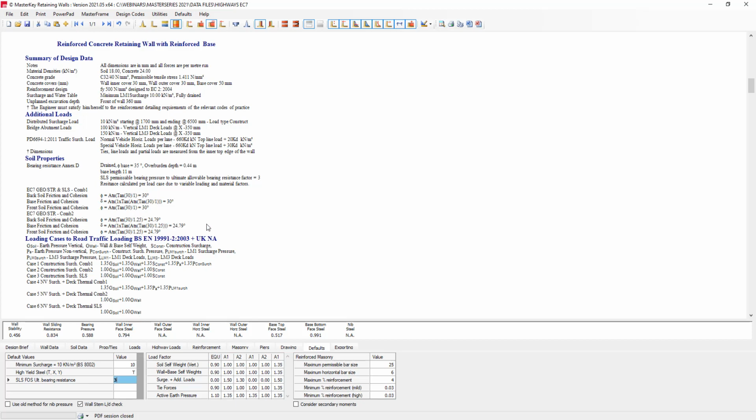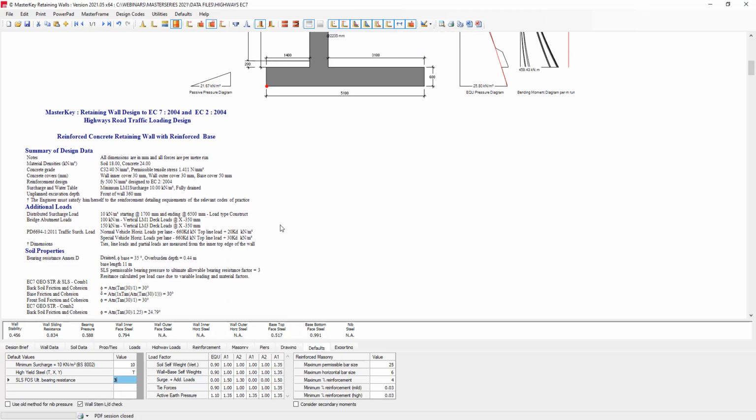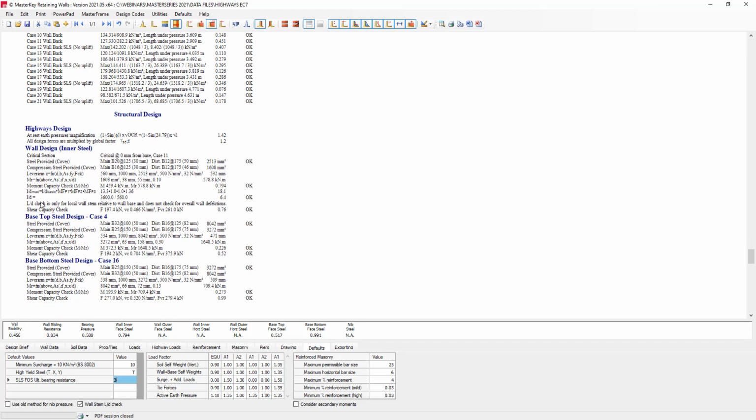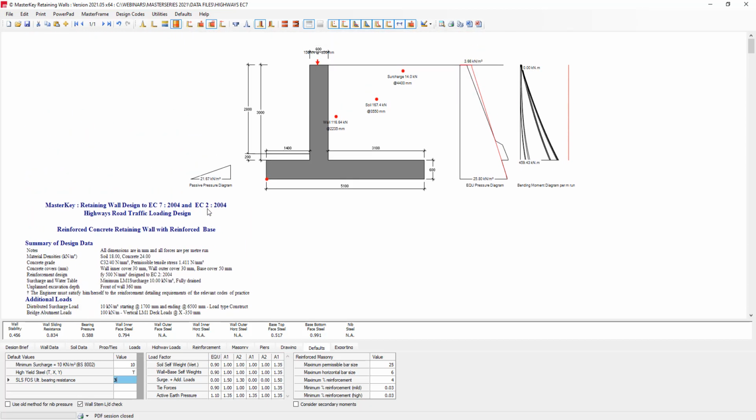And whilst the L/D check is useful as a check on the local span deflection, it doesn't take any cognizance of the overall wall movement. It's a check on the performance of the span relative to the movement of the base. So we do have a little caveat in the design output once we get all the way down to it. When the L/D checking is included, it is relative to the wall span and doesn't take account of the overall wall movement, which is a soil structure interaction thing and obviously much more complex and not included in the software.